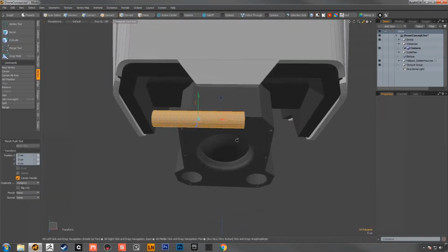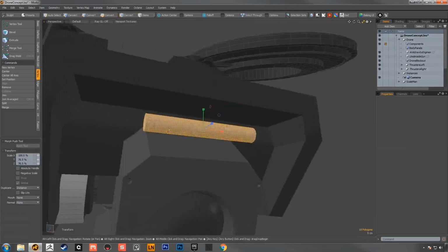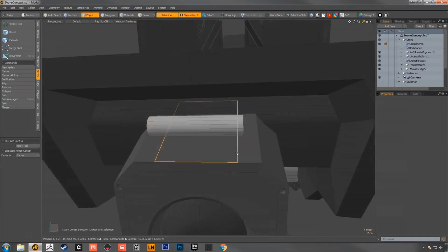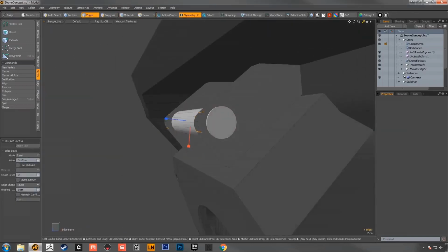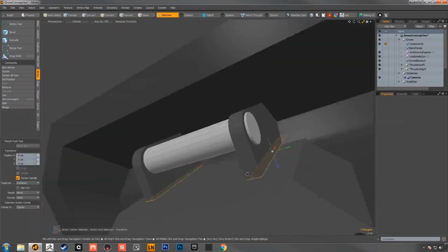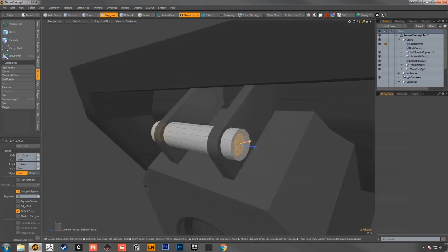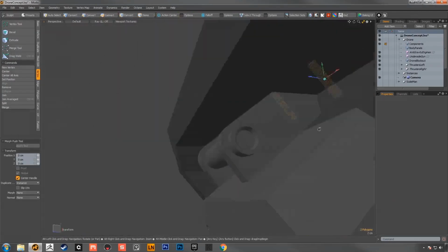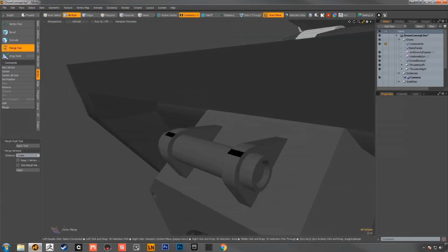One UV set, I'm planning on tiling all of my actual textures. So it'll just be tiling camouflage or tiling paint jobs or tiling metalwork, and that will tile all over the asset. And then the asset can use a second UV set to reference maybe a normal map that was baked uniquely for the components, or AO maps or masks that have been baked in order to help the material define where to be scratched and where to be rusty and where to be dirty.